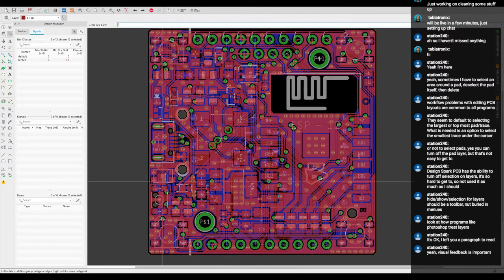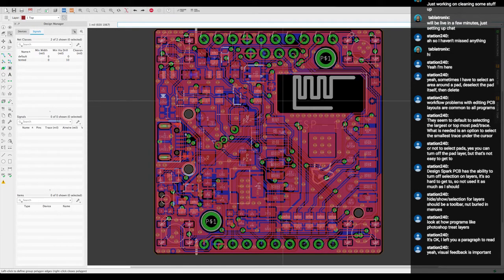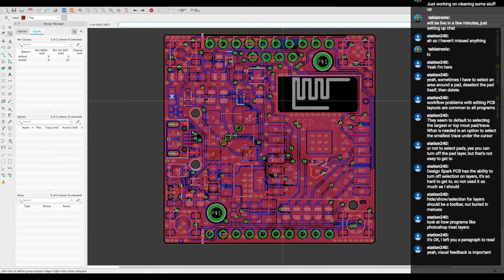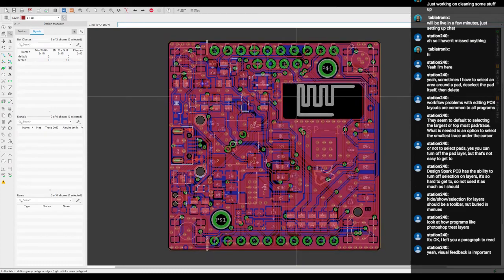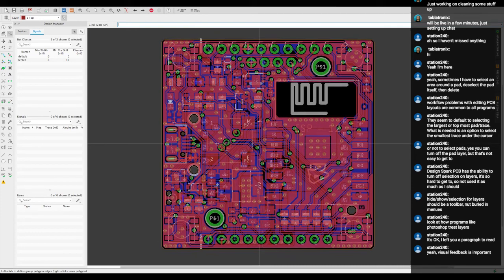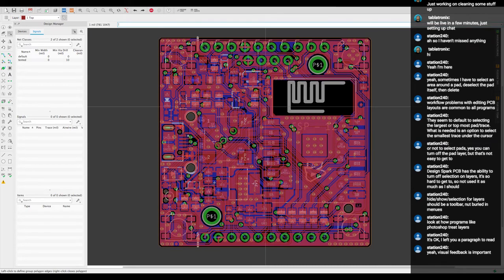And then I added that photodiode for photo sensing. That's the cheapest solution. I could add an I squared C ambient light sensor, but I think they're like $1.50, $2. These are like 11, 12 cents, I think. And you're just measuring general light. I don't really care about high motion detection or anything like that.